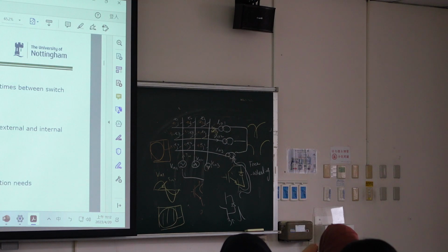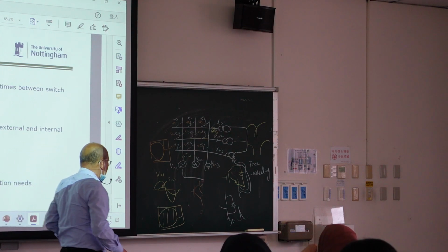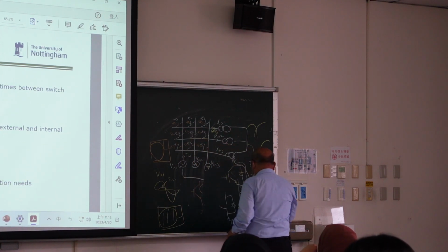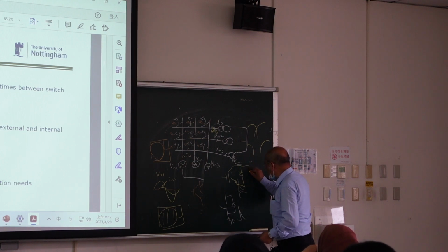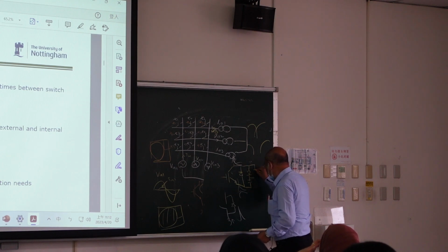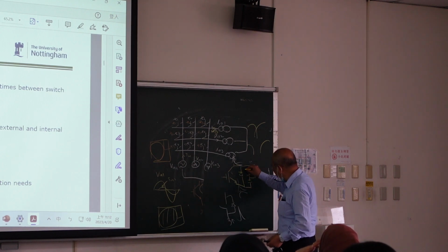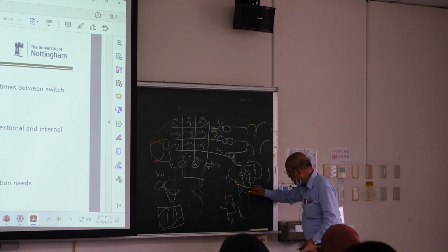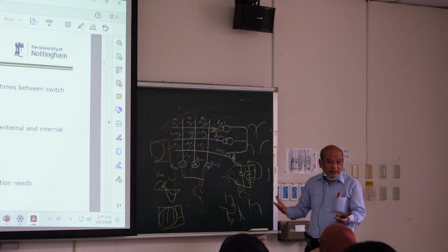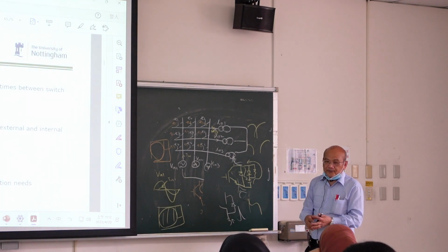Circuit protection. Before, you have a snubber. You can put a snubber here. You say, I want to protect my device. So what can I do? I put a snubber. If I turn off, then I can charge the capacitor. Then the capacitor can go here. Originally I have a spike, but now I can remove the spike by using the snubber.